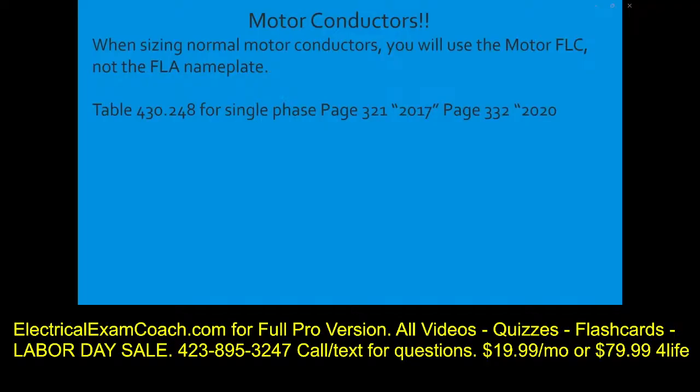Now, continuing to read the table from top to bottom, left to right, using the black bold headings to navigate the table, we're going to start on the left-hand side. And if you notice there, you have your horsepower. That's going to be whatever the horsepower of the motor is. Now, across the top, all of those black bold headings are respective voltages. Okay? So what you do is you go to your horsepower, and then you come over and you tee off with whatever voltage your motor or your question states.